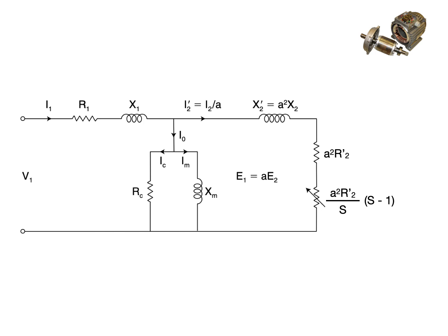The slip is the key performance factor. It measures how far the rotor lags behind the synchronous speed and directly determines the torque and the power delivered by the motor.